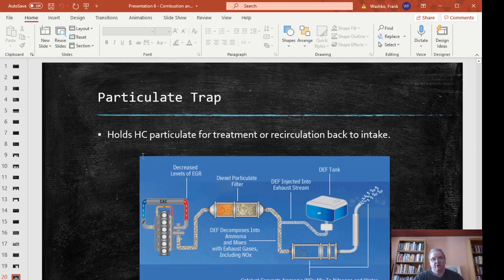If you see a truck going down the road blowing smoke, that's what's going on. Part of it's unburned hydrocarbons, and part of it is just carbon particles in itself. But you have these actual particulates. It's not really vaporized anymore. It's actually physical particles that you can trap with a screen or a filter kind of thing. And for the diesels that are really bad at putting out particulates, unburned hydrocarbons and carbon particulate, you'll have a particulate trap on the end also.